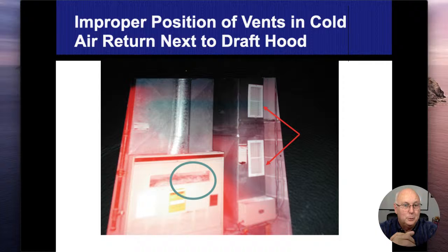So a solution to that, and not a very good one, but it is a solution, is somebody can cut in those openings that we're seeing on the return duct where those two red arrows are pointing. And that way we're not going to depressurize the rest of the ductwork. But then again, we're also not pulling air out of those rooms either. So that's going to make the air circulation from the rooms less efficient as well. I know the proper solution is actually expensive, which means putting in bigger ductwork or additional ductwork, and that's not something that people normally want to spend. So they try to go ahead and find a solution.